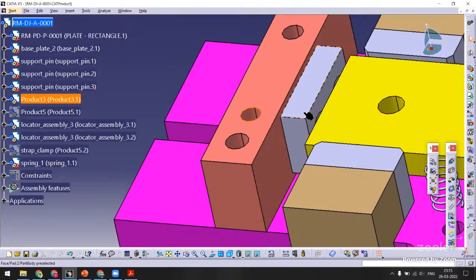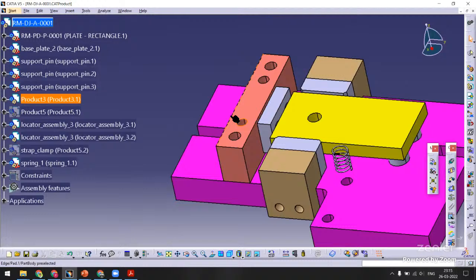If we want to put it back, if we want to put it front, how are we going to do it? Then what we need to do is put some shim behind this wear plate. What is a shim? A shim is nothing but a thin plate, a very thin plate, which could be inserted inside so that the wear plate will come forward. This is very important. We need to anticipate how our design could go wrong and then make provision for adjustment at a later stage after manufacturing.